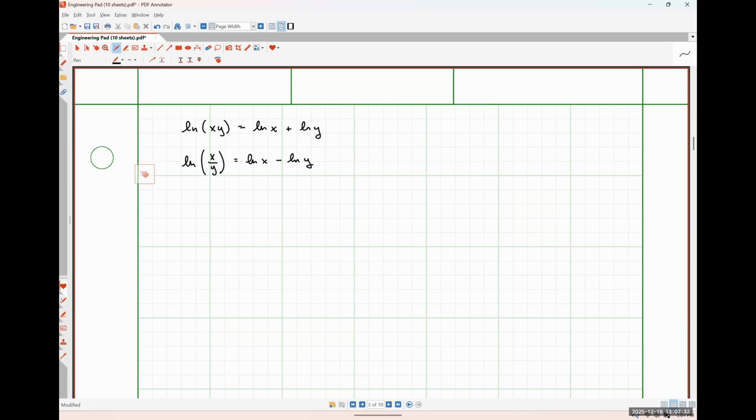Well, we know how to add signals together, and we know how to subtract signals. So if we can figure out how to take the natural log of a signal, we can perform multiplication and we can perform division. But then we'll have to take the anti-log or the exponential in order to actually get out the product of those signals or the division of those signals, okay?